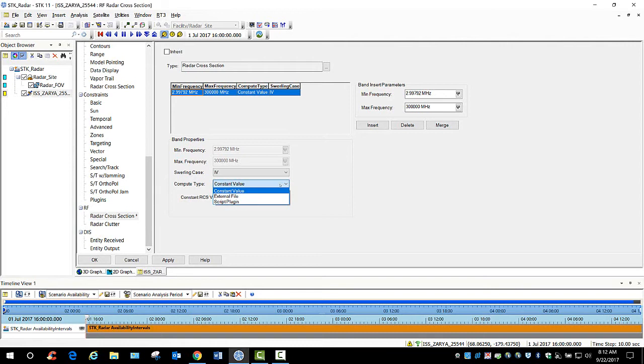So different targets out there, aircraft, for instance, satellites, have their own RCS file and signature, and that would give you more of a realistic scenario because the object flying straight towards you would give you one type of reflection. From the side, it would give you another reflection. From the rear, it would give you a different reflection, flying straight overhead, and so on and so forth.